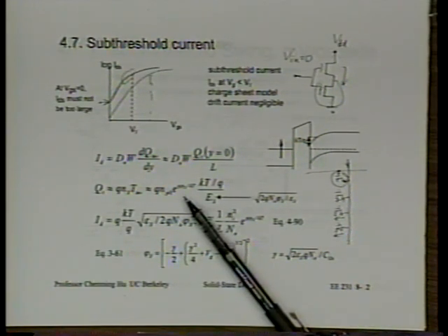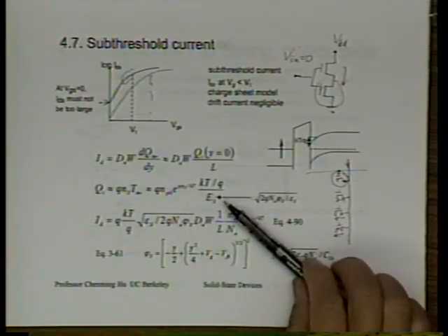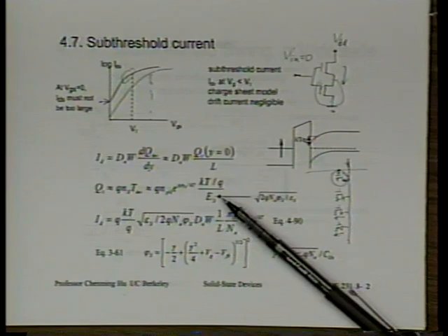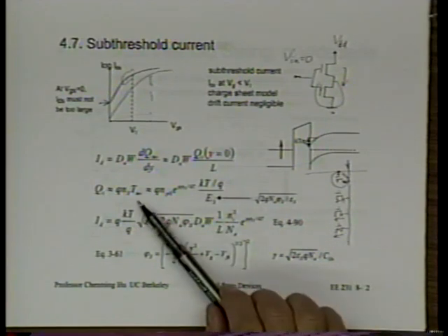Yeah? Okay. Next, we need the thickness of this layer. In other words, over what thickness do we have an electron concentration that's roughly equal to NS? Beyond that thickness, further below into the substrate, we have much lower electron concentration. So as a result, on average, we say that's the thickness we have to consider.